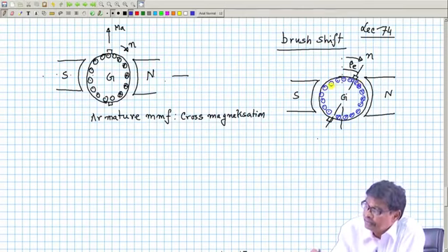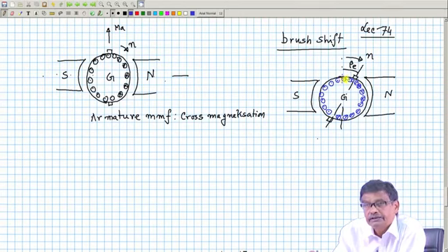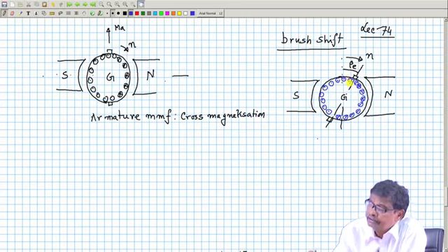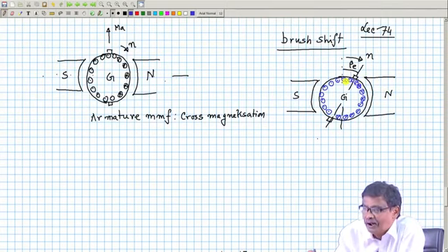Because the conductor's induced voltage under the south pole is of dot polarity, but this conductor is going into commutation, its current will switch over from plus I to minus I as it crosses this brush position. Therefore, this conductor started inducing voltage, dictated by this north pole, a little earlier when it crosses the brushes.